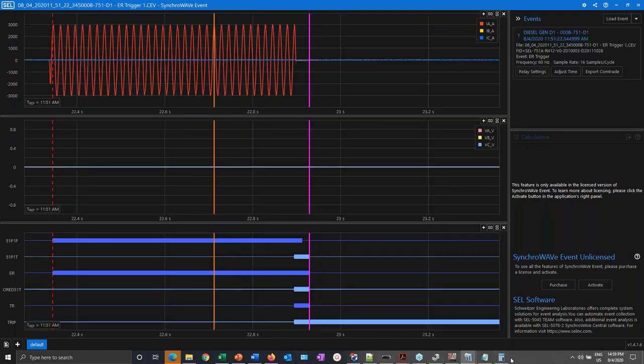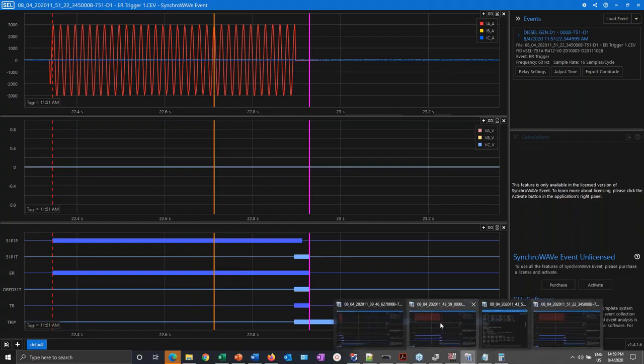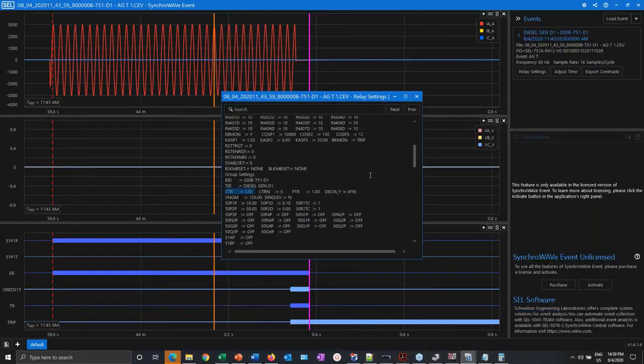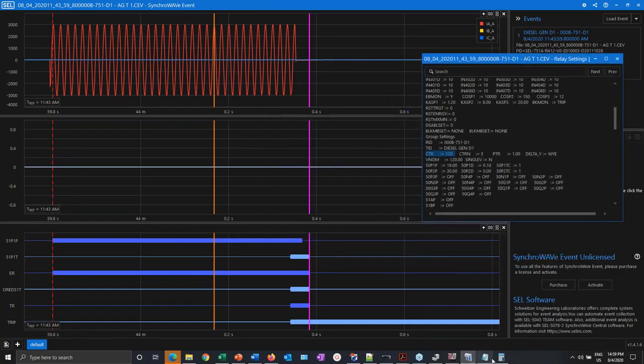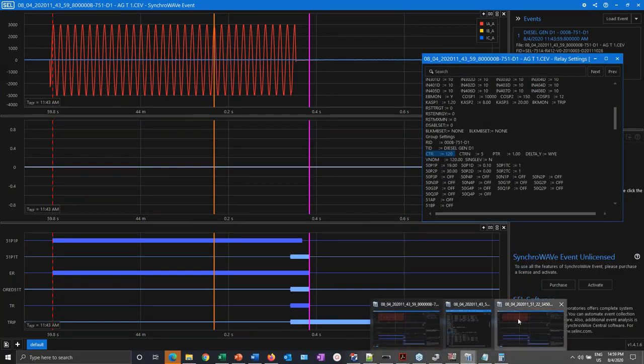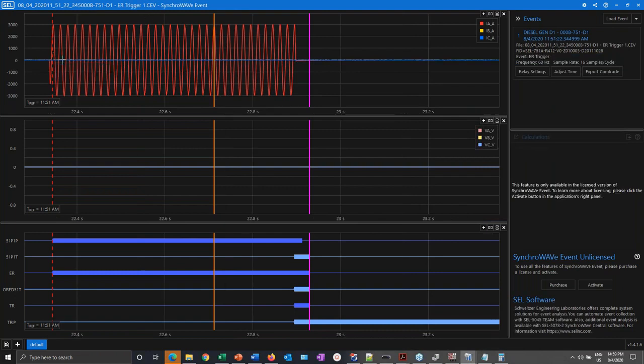So are they the same exactly? If you look at them, they look exactly the same, and the oscillography itself is no different. They essentially have the same oscillography. The relay started recording here. It took 3 cycles before it recorded anything, because there was nothing, and then recorded exactly what was being played back into the relay. But what is different now?